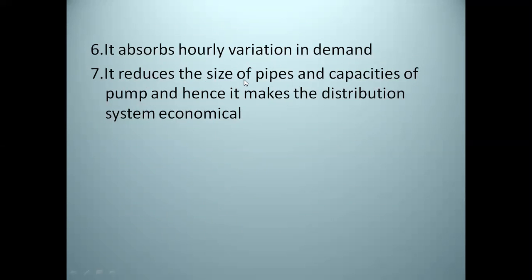It reduces the size of pipes and capacities of the pump, and hence it makes the distribution system economical. Due to the service reservoir there is a high pressure to the water, then it can reduce the size of pipe, it also reduces the capacity of pump, and it can make the distribution system economical.